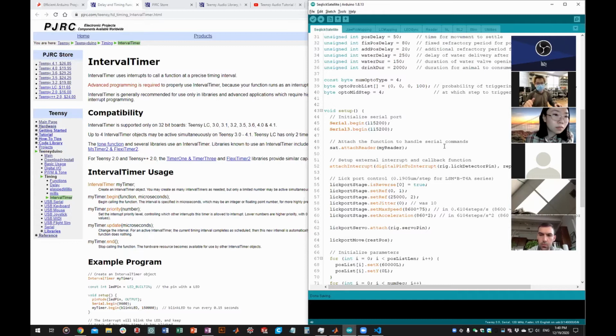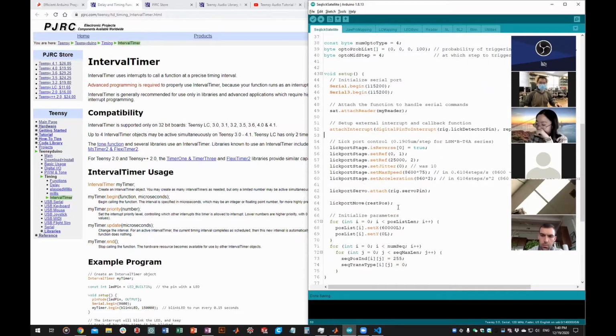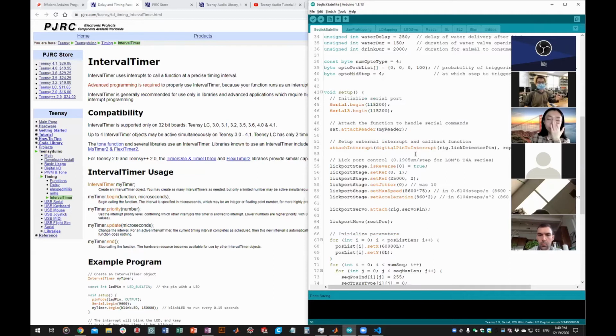So what is a timer? A timer is an internal event that's generated once the counter reaches a pre-specified value. The counting of those counters is in parallel to our actual code, so that's a kind of parallelization. When the counter reaches the limit we set, it triggers an internal interrupt, or timer interrupt. If you associate a function with that timer interrupt, that function will be executed at that point. Everything up to here is kind of abstract.